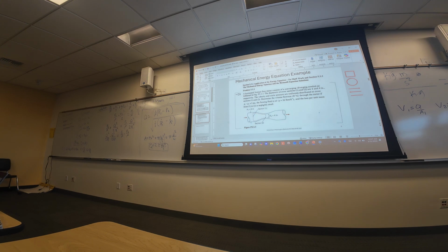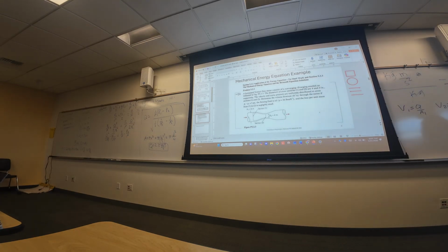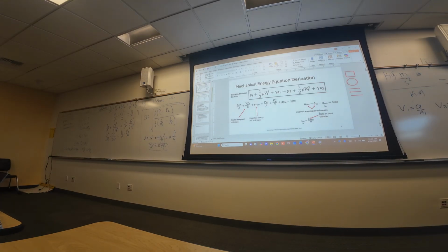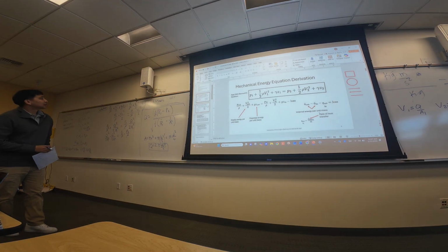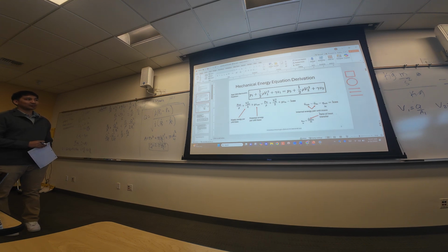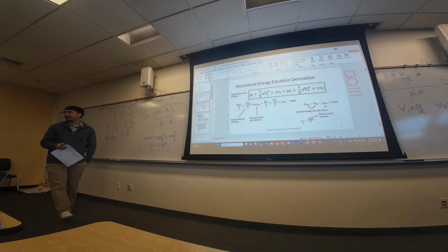Okay. Any questions? Yes. Couldn't we just use the old equation to solve this problem? Let's see. Yeah, I believe so. That's a good point. You can. This was the original Bernoulli's equation. It's a little different because you take out the density, but that doesn't matter too much. So yes, you can, because we assume these are 0. If we assume these are not 0, you need the new one that we derived. Good point.